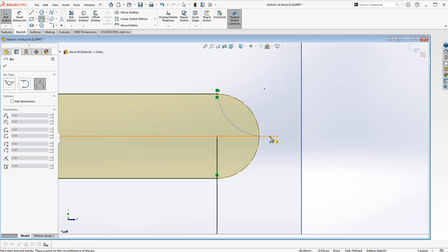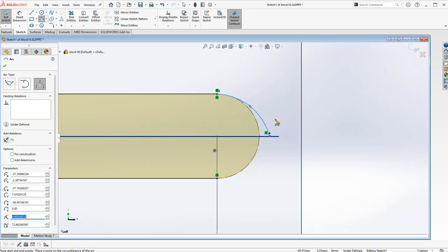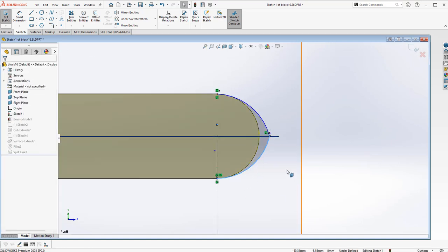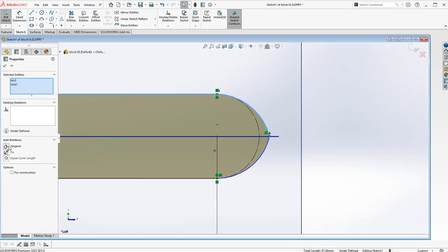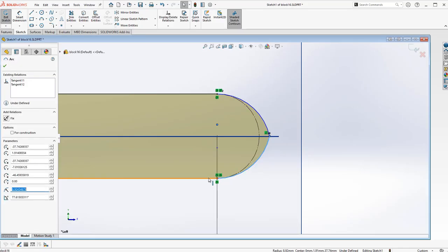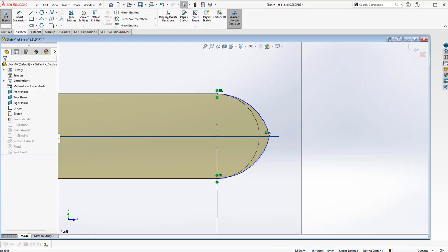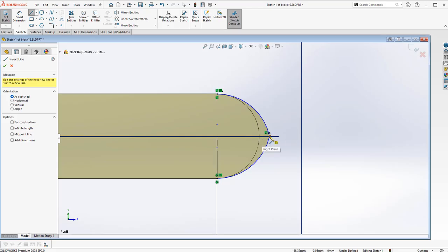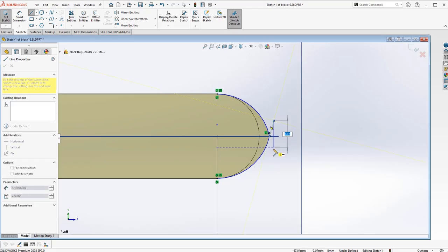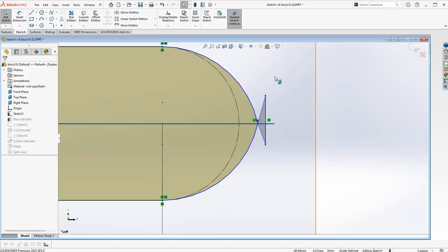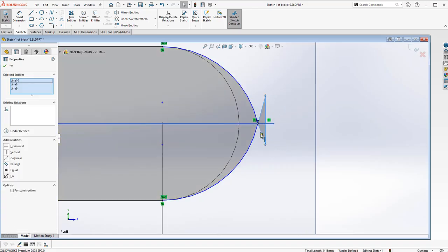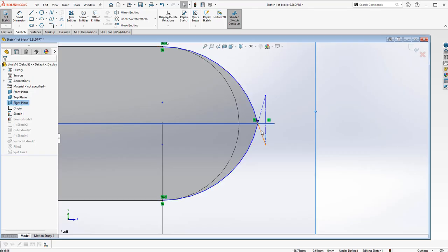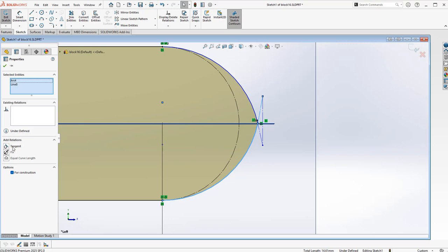This is something we do in forging and plastic part design quite a bit, especially as we take things from an R&D perspective and push them into manufacturing. So here what I've done is I've created an eyelet. I'm going to go ahead now and establish tangency at the top and the bottom. I'll put a leg on this geometry so I can establish tangency on all three of these faces. I'll turn that to construction geometry. Let's establish tangency across here and here.